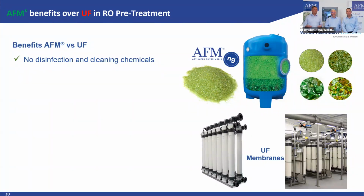So what are the benefits of AFM versus UF? No disinfection or cleaning chemicals. So we don't need cleaning chemicals. Why not? Chemical enhanced backwash is a typical process you need to do with every membrane. That's required by the UF membrane suppliers. That's really to clean the UF membrane, mainly for biofouling. Again, it's a biofouling issue here.